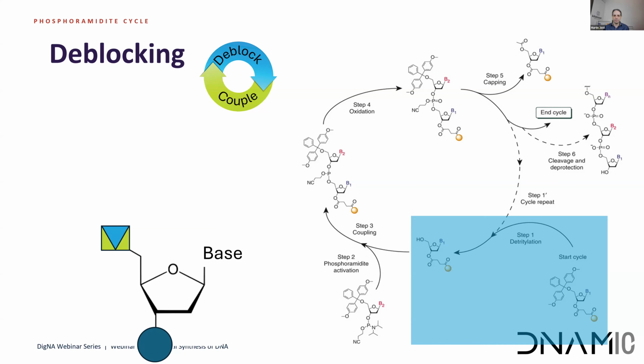So what we did is we transformed the concept to injection molded polymer chips. The liquids are actually actively controlled with pneumatic on-chip membrane valves. The benefit of all this is that the fluidic channels are embedded in a disposable chip. Everyone who ever operated a classic synthesizer knows that the tubing and valves need constant attention and maintenance. Not with the chip. This is just thrown away after synthesis.